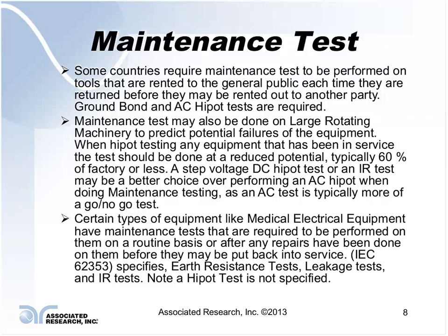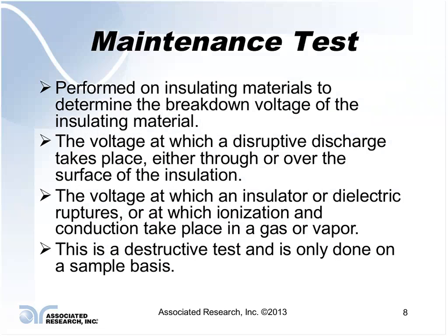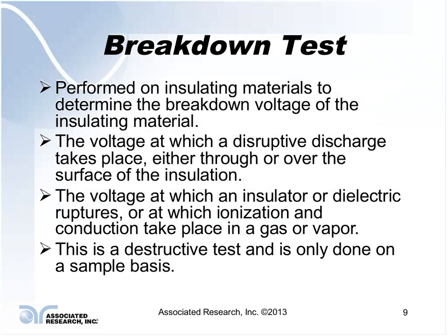Again, when doing those tests, do them in accordance with the standards. Don't just make up some numbers. If you're doing them according to the standards, you've got tests that have been chosen based upon some actual history on different types of insulation and different types of product. You're not using a one-number-fits-all approach, because that doesn't verify whether the insulation is good or not.